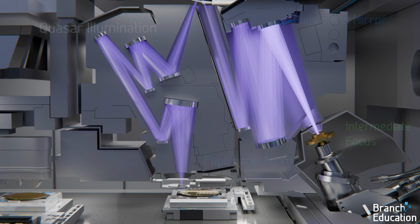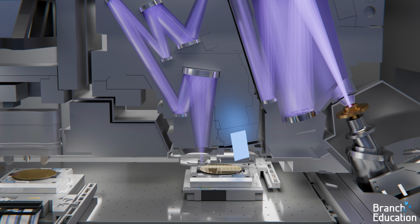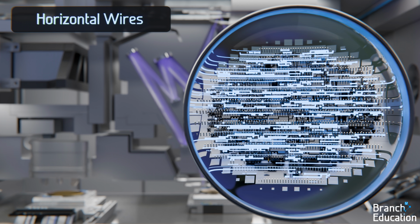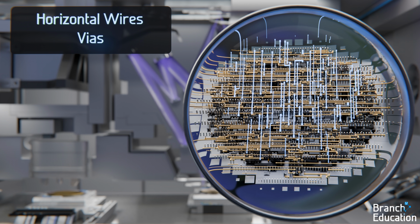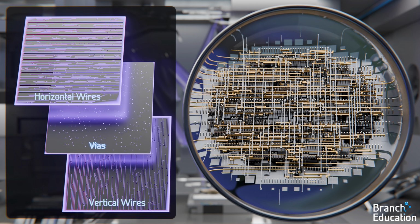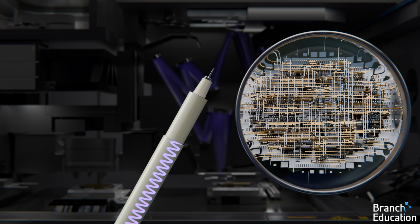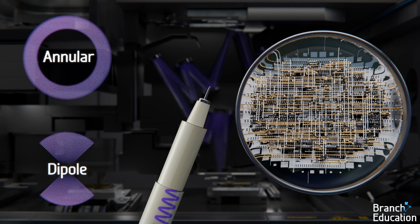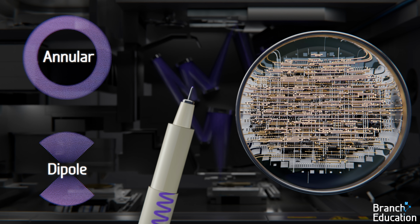You're probably wondering why we require such complicated patterns of illumination. Well, when we look back at the microchip, one layer of wires is running mostly horizontally. The next layer is a set of cylinders called vias. And then the following layers have wires that run vertically, and each layer uses a different mask. Earlier we said that the EUV light is kind of like the tip of a fine-tipped pen. Having different patterns of illumination is like holding the marker at different angles, with respect to the lines or circles that are being patterned.